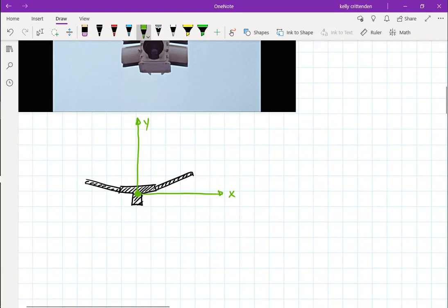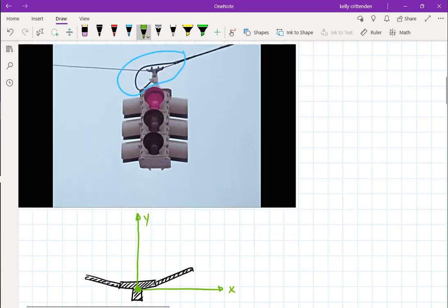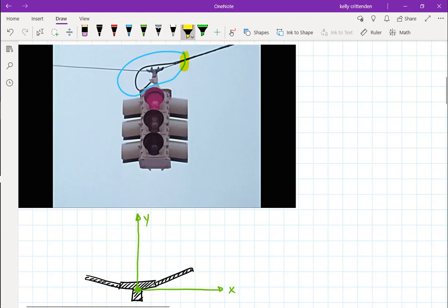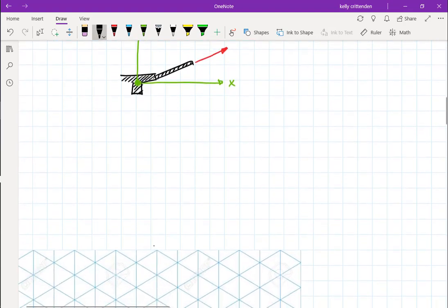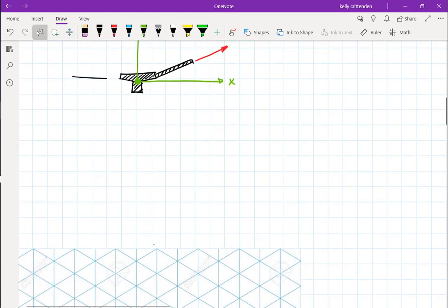Replace all the cut things with some kind of force or torque. Now in here, we're not dealing with torques or moments yet, so just forces. So I cut through right here, and I have to replace that cut connection with some kind of force. That's a cable, and it looks like that cable would just have a tensile force in it. Tension is going to be an arrow that points away from the body, and now that I'm looking at my picture, maybe this one's supposed to be a lot more horizontal. So let's make it way flatter.